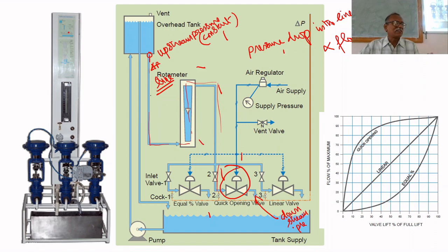Flow rate is like current. If current varies, the drop in the wire will vary. Like that, the pressure drop will vary. That's why the pressure just before the valve varies, where the flow enters the valve.